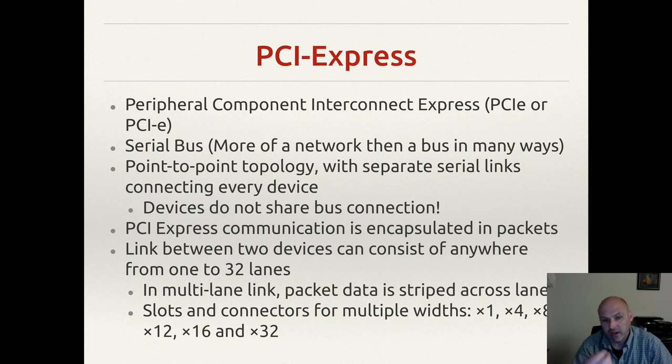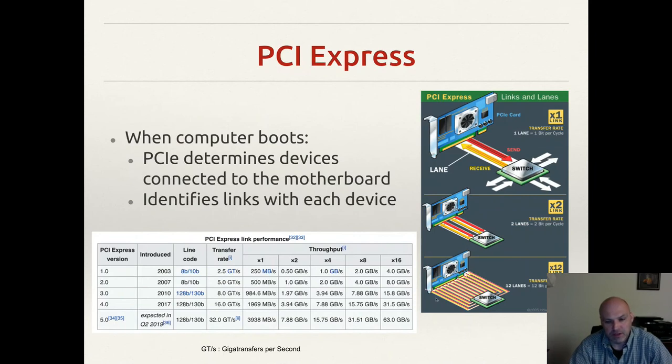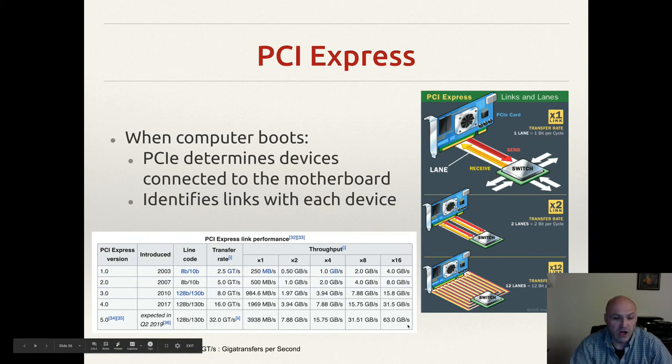So that means in a parallel nature, it can use four serial buses to individually transfer information, and you're getting 4 times the speed. But there's still 4 independent serial buses with all the advantages that come with it being a serial bus and not a parallel bus. You can see here too that the speeds on PCI Express are just insane compared to anything that's come before it. We're now up into, if you had a 16X card, up into the 63 gigabit per second range.